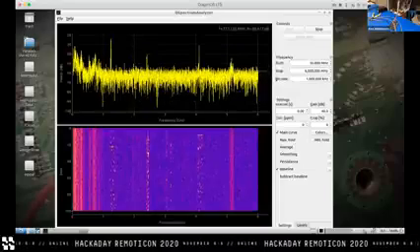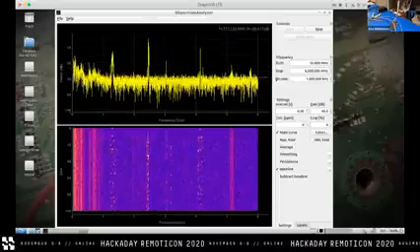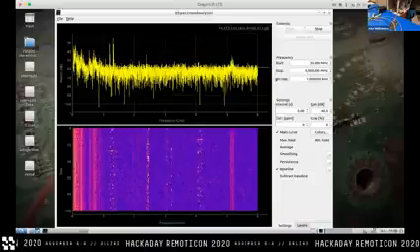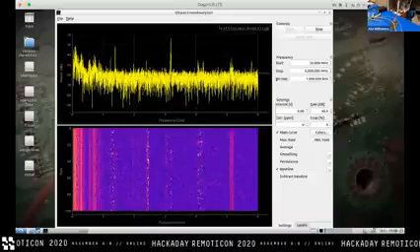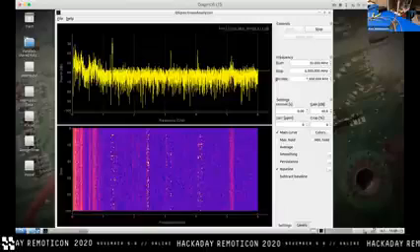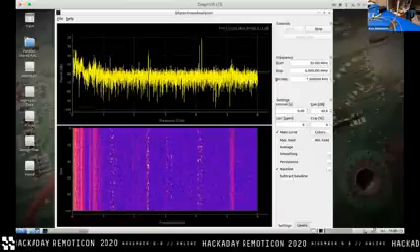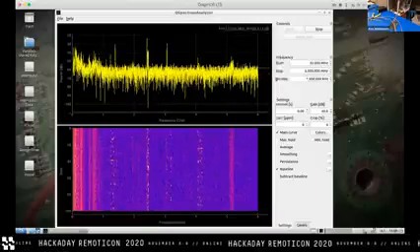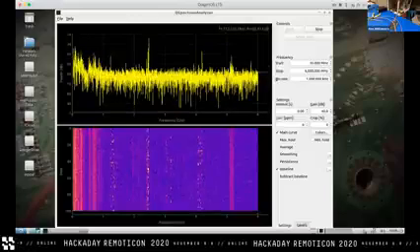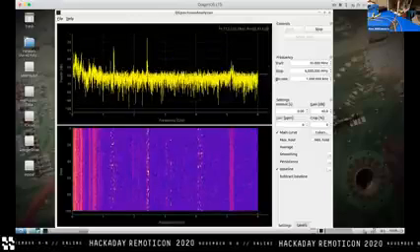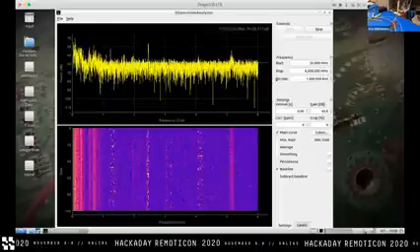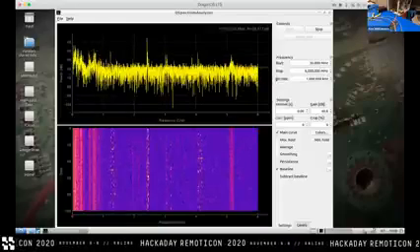But with the RTL-SDR and whatnot, the noise floor may be different, the gain may be different at different points in the frequency spectrum, and all of that is going to kill you if you're trying to do actual calibrated pre-compliance checks. We avoid the need for that entirely because we're just qualitatively looking for where stuff is coming from. So you'd probably run into that as a problem.